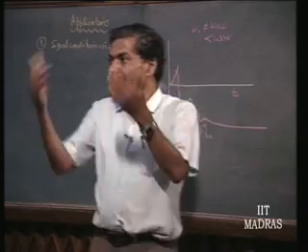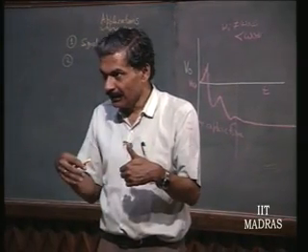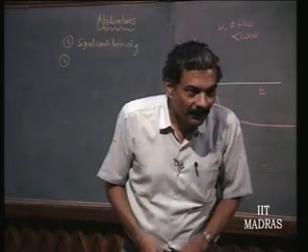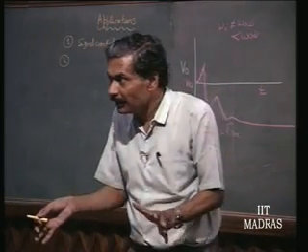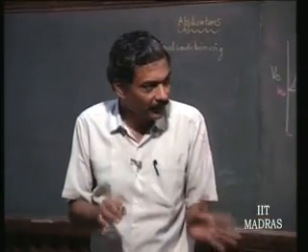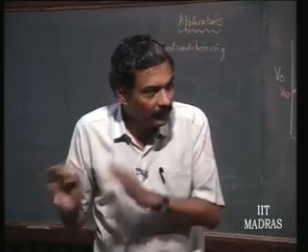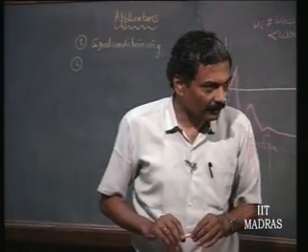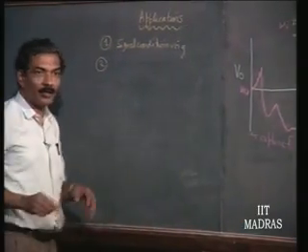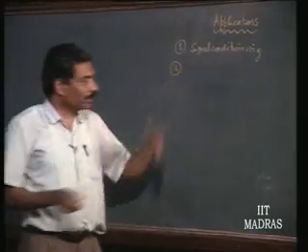And so, you can extract the synchronization frequency from the composite video using simply a phase lock loop running at the corresponding free running frequency corresponding to the horizontal synchronization pulse or vertical synchronization pulse frequency. Okay. So, that is also forming part of signal conditioning or FM detection, right.